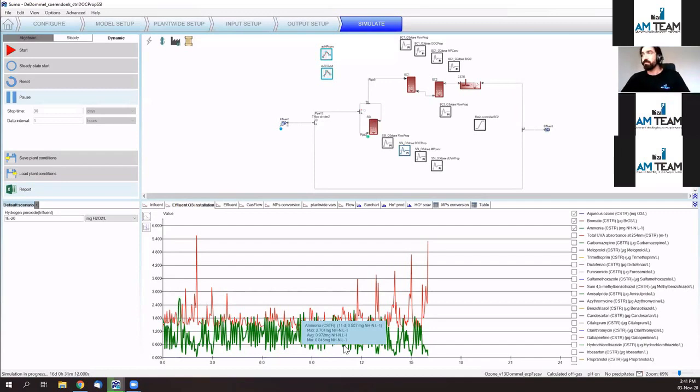And what is interesting to see here, which Wim will also mention again later, is the ammonia influence on bromate, because of the formation of monobromamine and dibromamine, which is sequestering bromide ions.